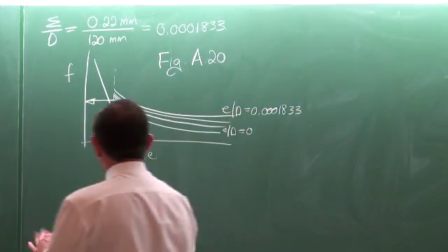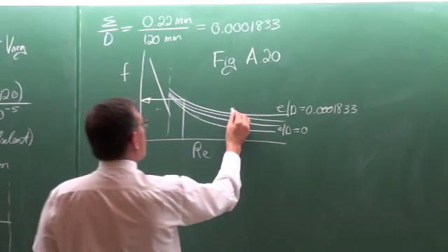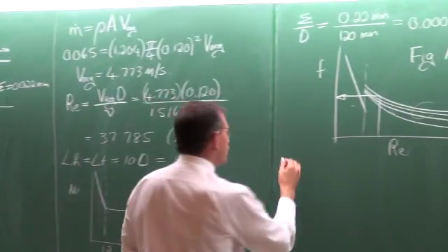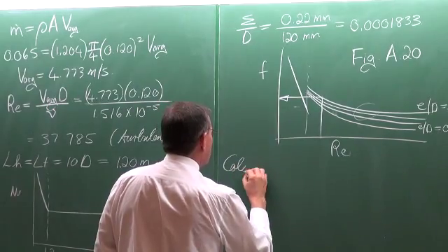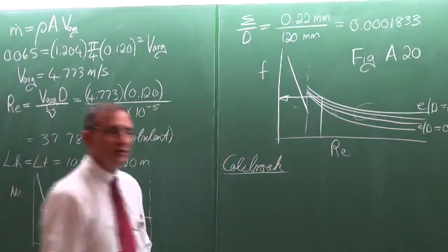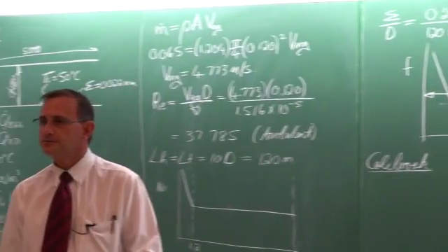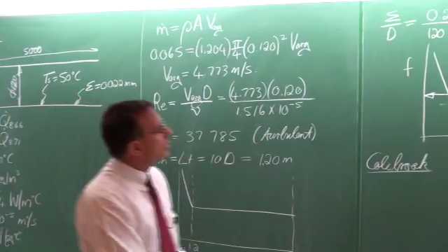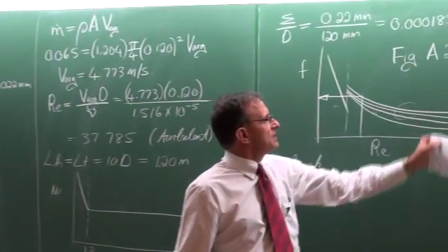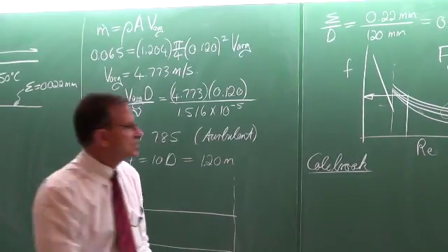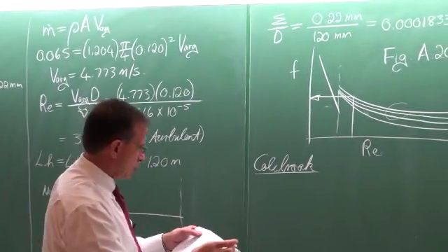So an equation which gives us the friction factor for all these other equations is the Colebrook equation. I don't know if you've done it in fluid mechanics. It's just an empirical equation, and it is also in figure 820. If you read at the bottom of the figure, you'll get the equation there, and it is in your textbook also.